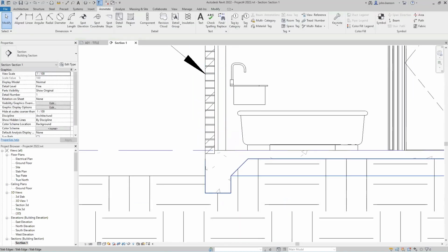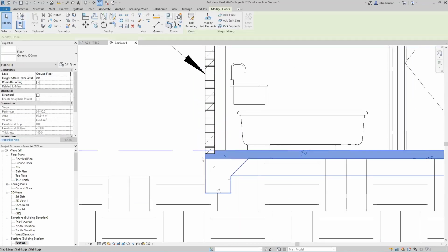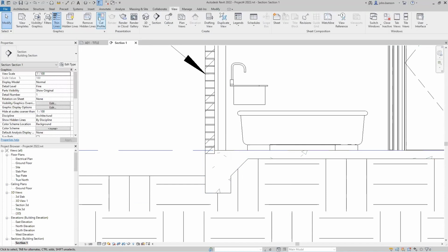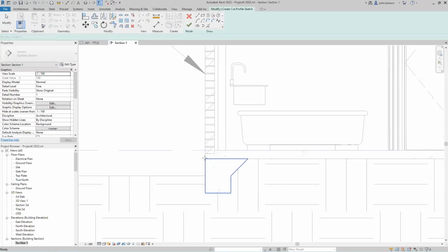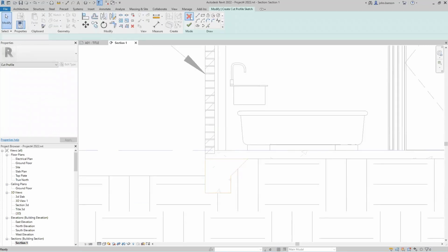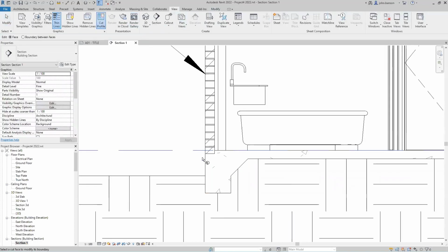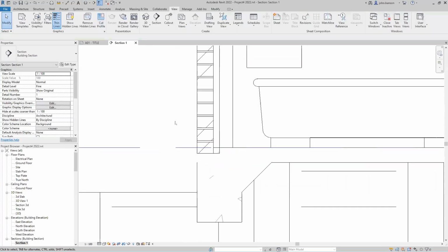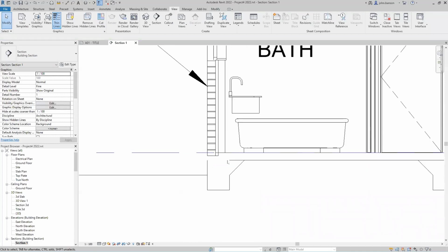And then this is where the cutout tool can apply too. So I can put a cutout on that concrete slab. Oh, wrong one. Slab. And then I can go from there. And so now that's cut out.